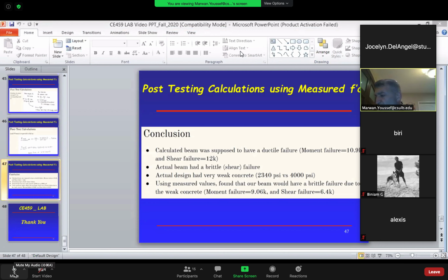Okay. That's 119 total dead load, pounds per square foot. That's the dead load of the slab. Am I correct? Yes, absolutely. So once we calculated the dimensions for the beam, and then we use the 119, that's the dead load of the slab on top of the beam. Am I correct? Yes, that's the weight of the slab going onto the beam.